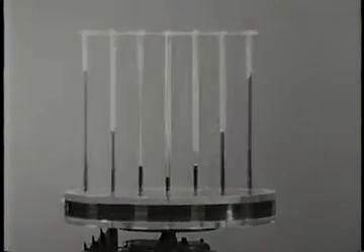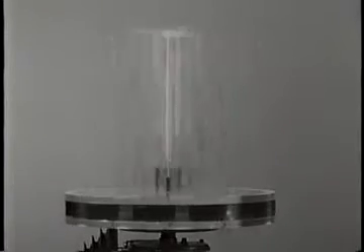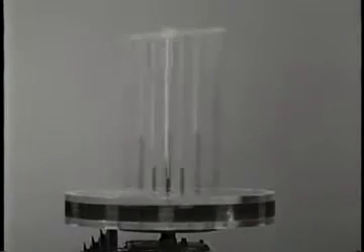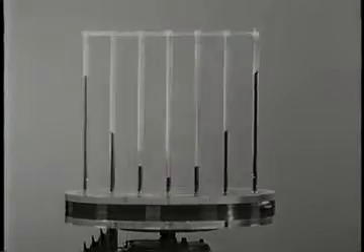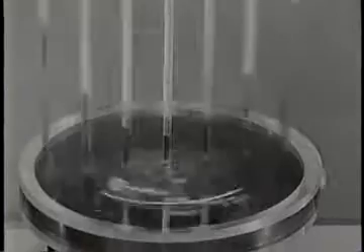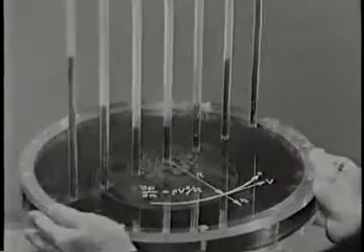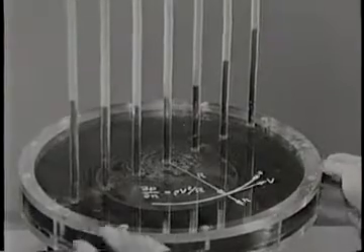The right way to look at this is with our familiar equation relating to streamline curvature. The outward radial pressure rise produces the net force which accompanies the centripetal acceleration.